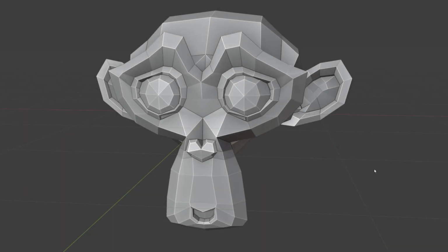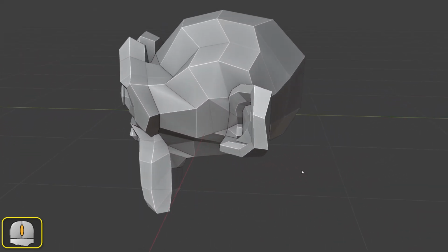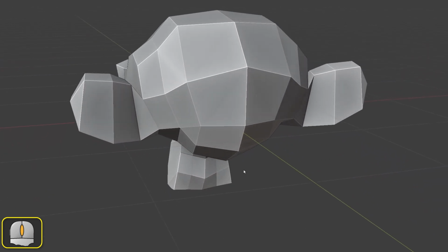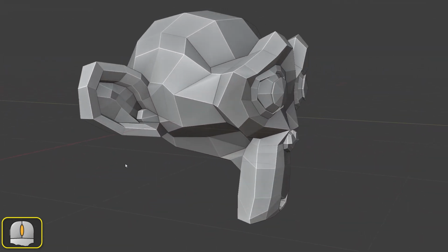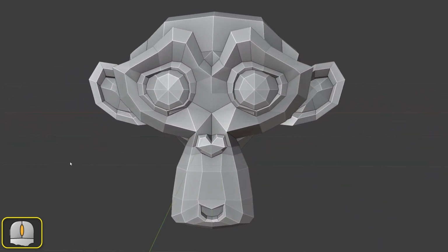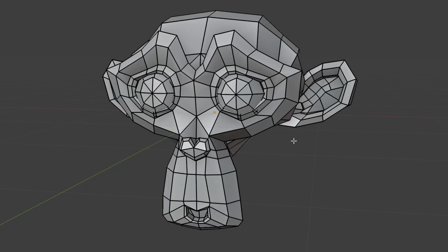When an object is made up of 2 or more meshes that have been joined using Ctrl-J, you may remember we did this in video 26 when creating our axes set model. The individual meshes that make up the object are sometimes referred to as islands, since there is no common connecting edge between each mesh. When in edit mode, we can select any of these separate meshes by moving the mouse pointer into any location within the island to be selected and pressing L. As we can see from this example, the eyes of Suzanne are separate meshes from the remainder of the head.